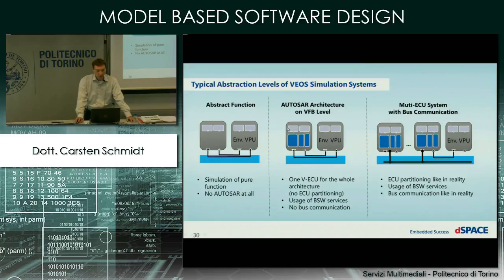And you would not use a bus communication, but everything, internal communication here, is done on the RTE level, so on the virtual function bus level.